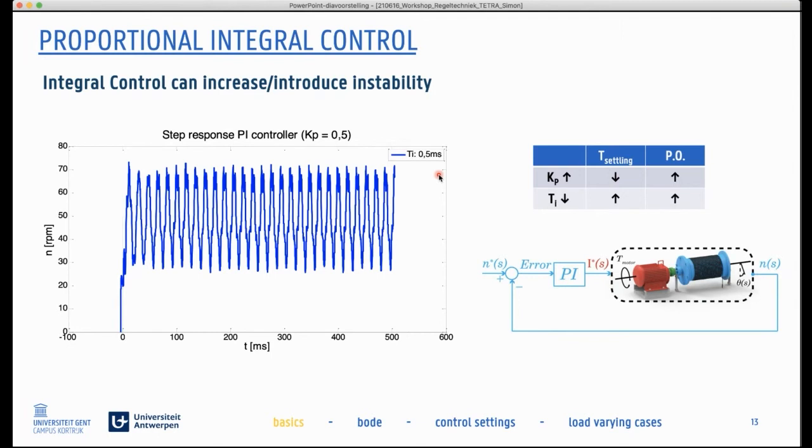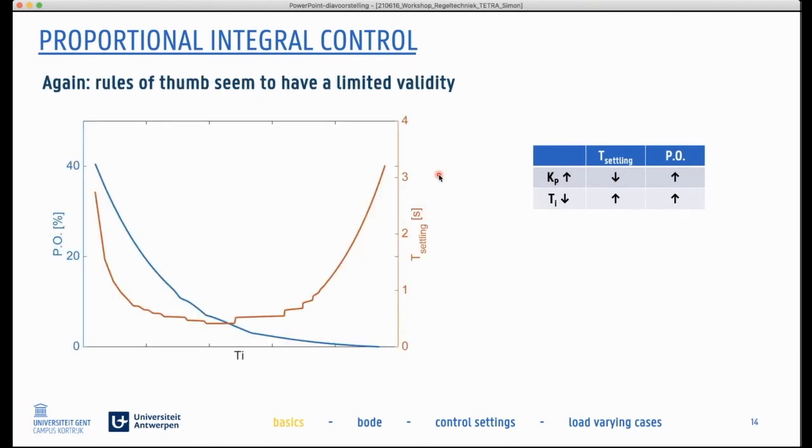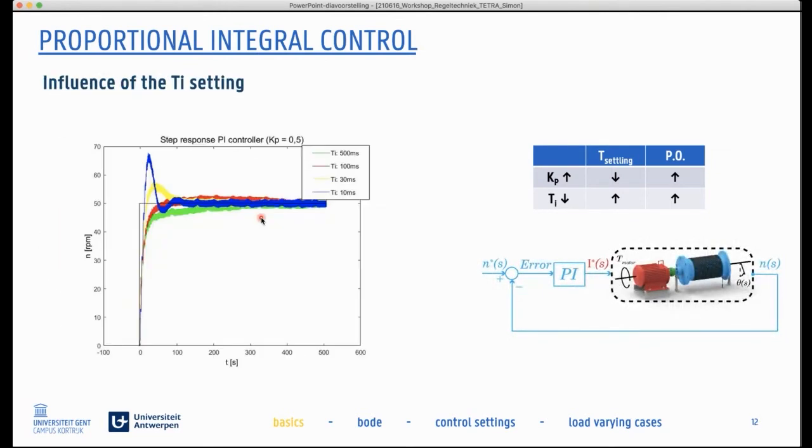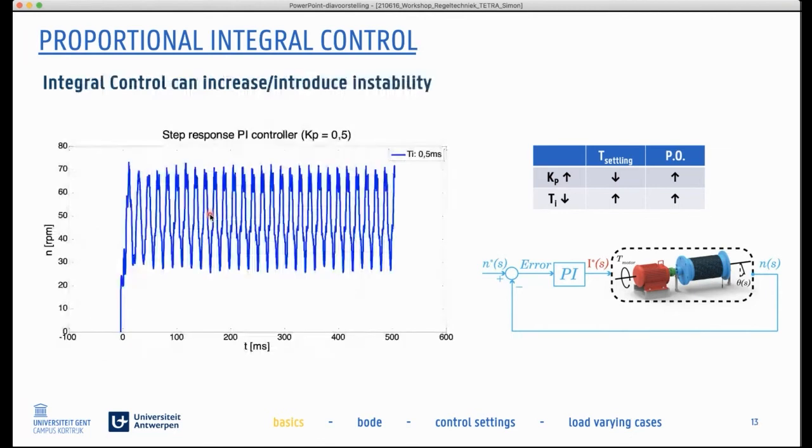But in many cases, you will need it, almost standard. It's almost default that you will need it, but I will show you how to know when you need it and when you don't need it. Well, if you need it, then be careful with the integrator. Be really careful. Start with a large value of Ti, decrease the value of Ti little by little. If you have the green response, the value of Ti is too large, then decrease it little by little to have a good response. But once again, these are rules of thumb.